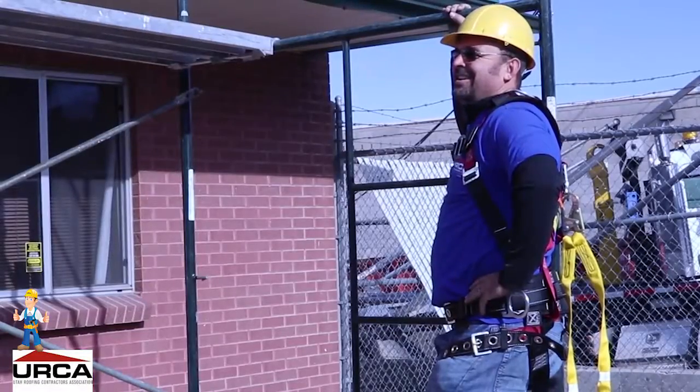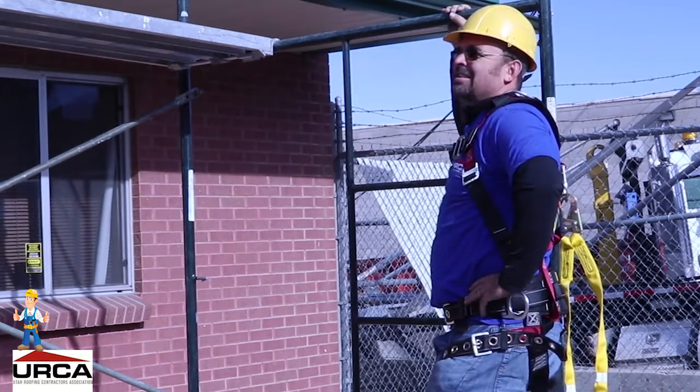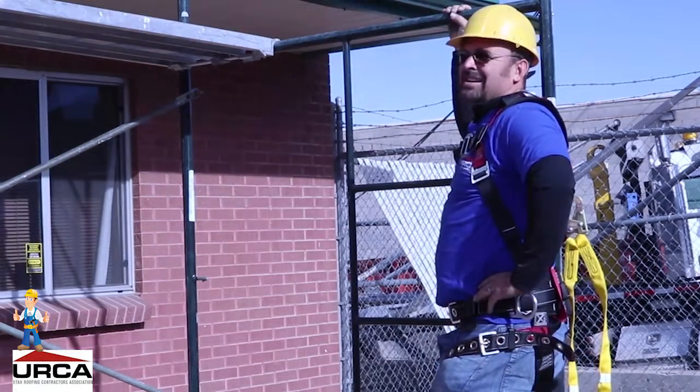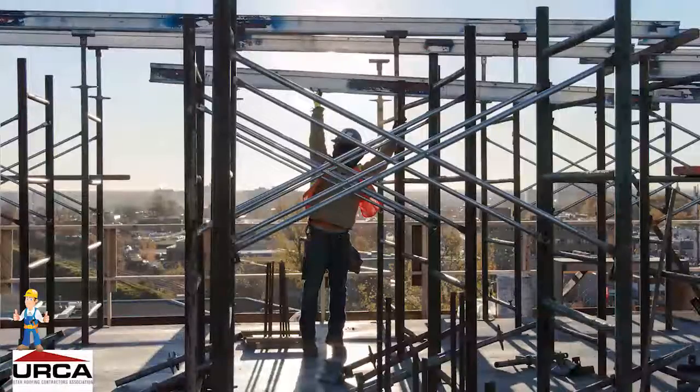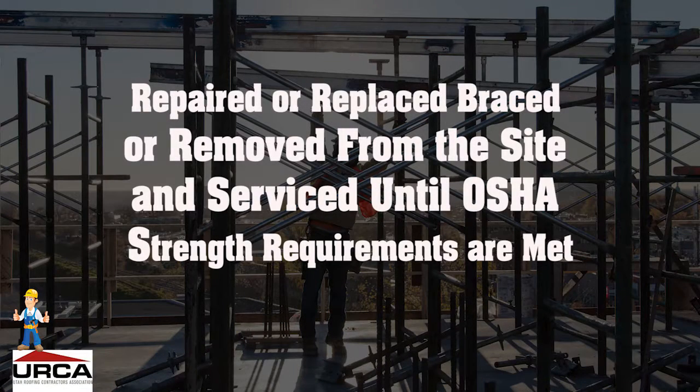They are responsible for inspecting scaffoldings regularly for visible defects before each day's work and after any occurrence that could affect the scaffold's integrity. Any part of a scaffold that has been damaged must be repaired or replaced, braced or removed from the site, and serviced until OSHA strength requirements are met.